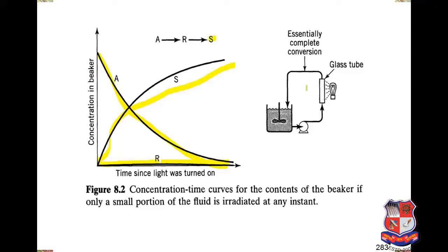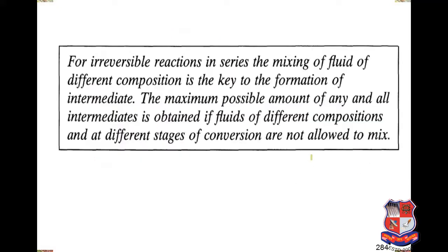So if our interest is in R, if the desired product is R, then definitely this contacting pattern is not going to be a good one. Yes, if you are interested in S, then it's fine, but if you are interested in R, this is not going to be a good contacting pattern. So for the irreversible reactions in series, it's very clear.